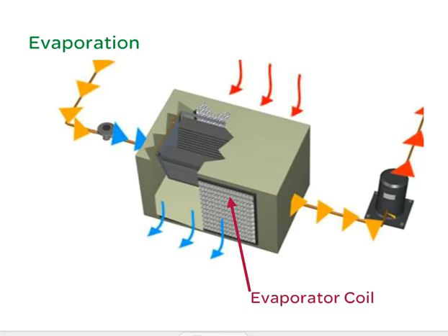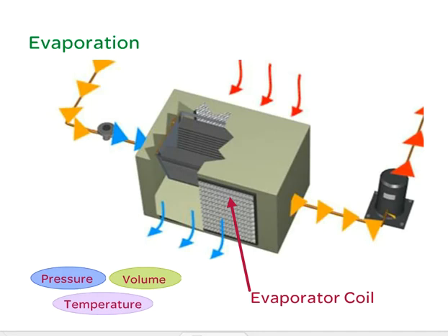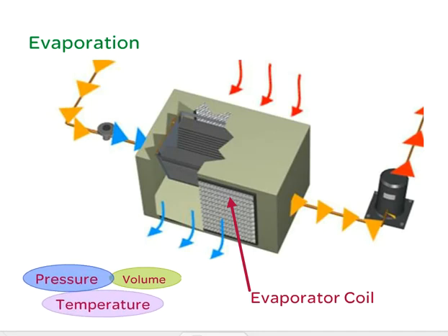Even though the evaporator coil is cold, at approximately 46 degrees Fahrenheit or 7.8 degrees Celsius, the refrigerant inside is evaporating or boiling, changing from liquid to a gaseous state. It is the heat from the computer room that is boiling the refrigerant, passing heat energy to the refrigerant in the process. The refrigerant at this point is a cool gas in a small pipe that is carrying the heat energy away from the computer room.